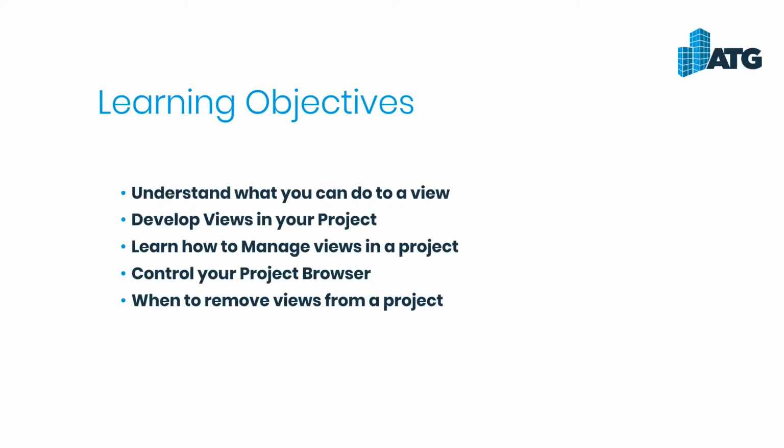We're going to take a look at the project browser and how we can control how that looks while you're in a project. So obviously that's going to affect how your views show within the browser. And then also, when should we remove views from a project? Sometimes, again, you can have too many views. When's it time to go in and remove views from a project, and what views can we remove from a project?